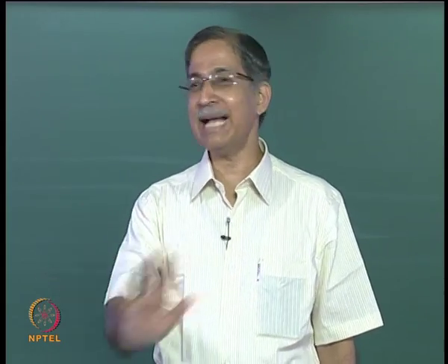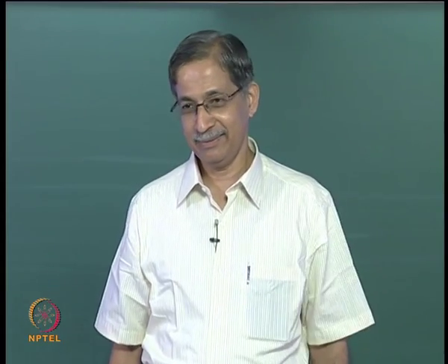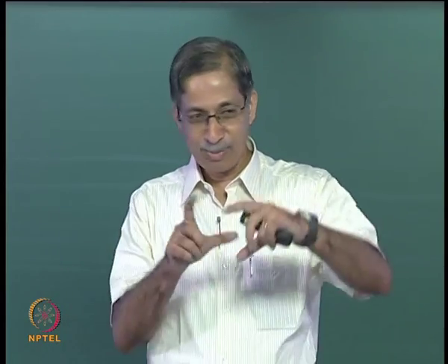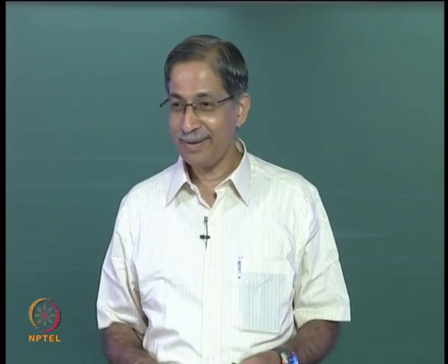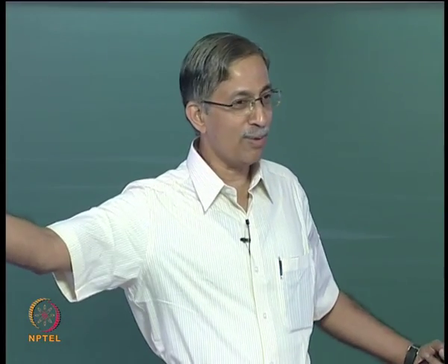The stiffness matrix has to be symmetric. We proved it. It won't be banded. It will be all over the place. It doesn't look nice. You can't put it nicely. So you want to make it banded. It may still be banded, but the bands are far apart, stretching to the extremes. You don't want that.